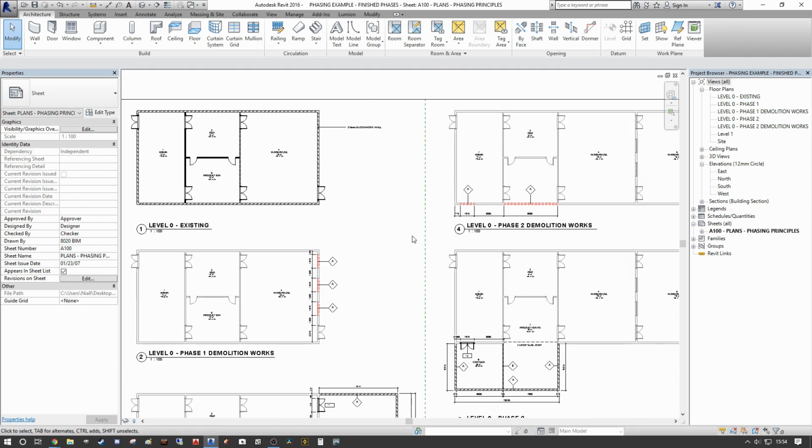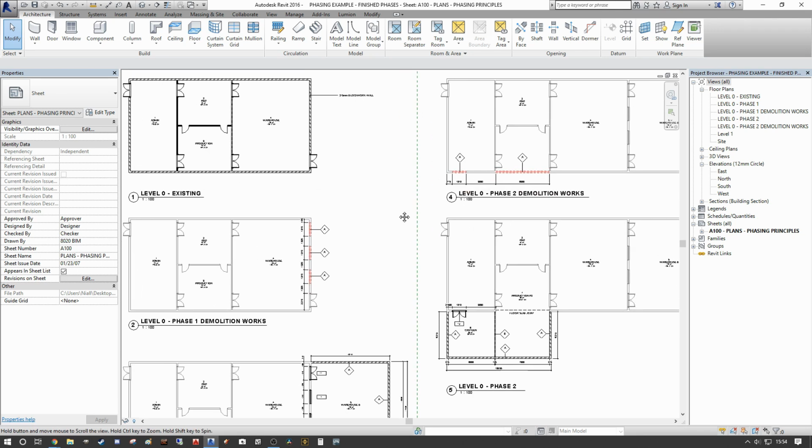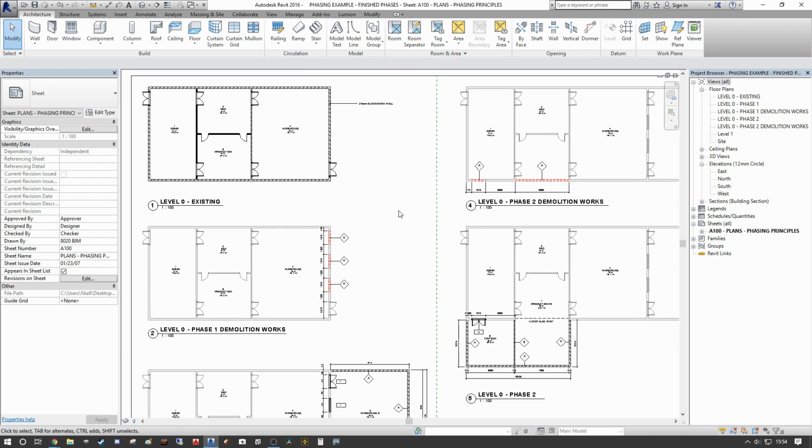So the idea is that we want to actually circumvent this. We want to actually streamline this. So we're going to create a generic annotation family that makes general text notes more Revit-y essentially, and gives us a schedule that we can update the fields within and therefore update multiple drawings at the same time. So I'm going to go through how we can do that.